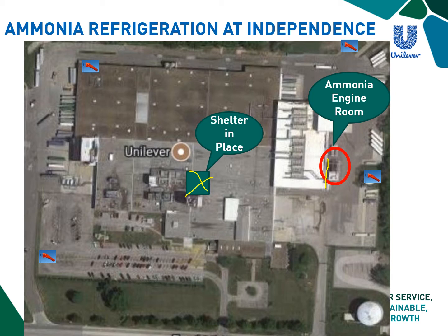If you were to meet possibly at our normal fire drill rendezvous point over here, and let's say the wind changes direction, that could potentially put the whole plant at risk of being in that ammonia cloud. So the safest place to be is in that shelter in place location. And as you all know, we shelter in place when we hear an intermittent alarm.